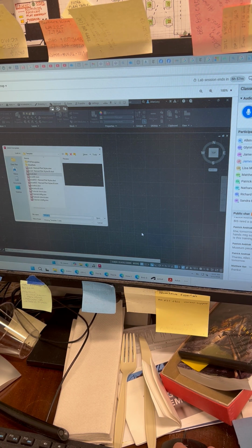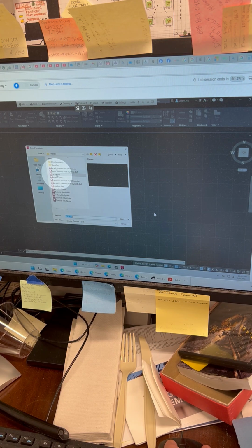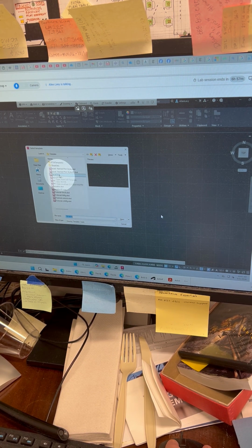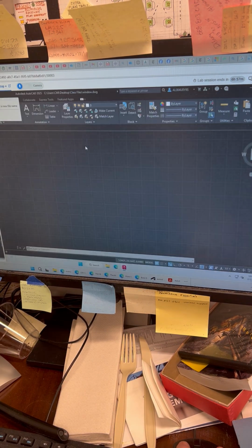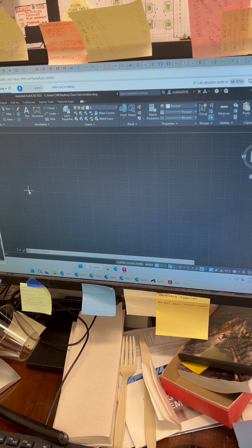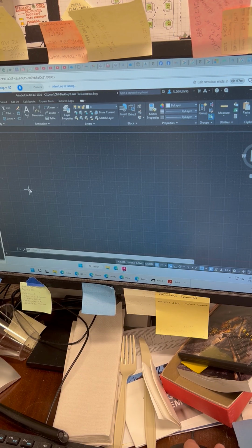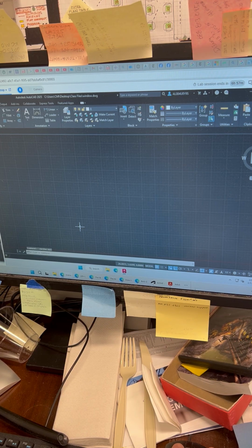By default, when you either do it this way or hit the plus sign, it's still using the AutoCAD template. As I was saying, I need everybody to turn on this drafting aid, ortho. Just click on it once. You'll see it turns blue. That means it's turned on.